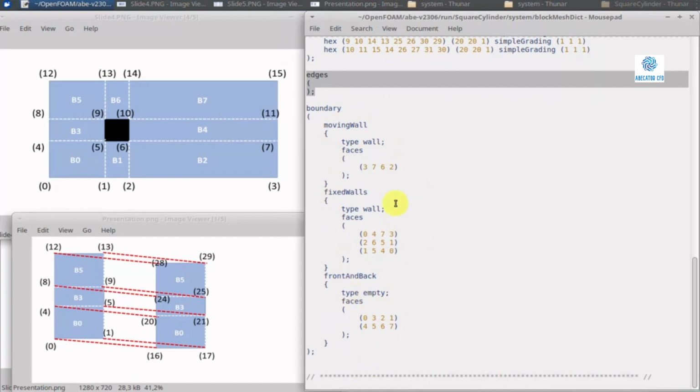The first boundary I want to define is my velocity inlet boundary. The boundary on the left side of the shape, I'll name it inlet. Its type is no longer wall. As you remember, we said that if our boundary is for the velocity field or the pressure field, in OpenFOAM we should use the term patch. With patch, I tell the software that this boundary either gets a velocity value or a pressure value, so it's